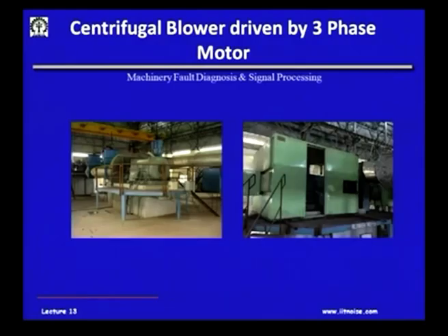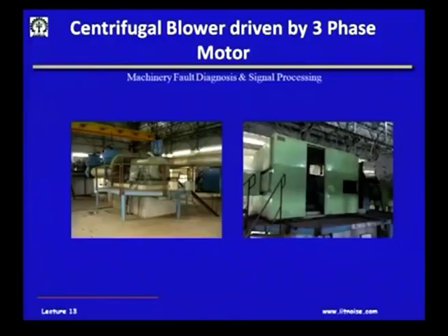Now, in this single room, because there are 5 blowers, what happens if one of them is running at a frequency or a speed little less than even 1 RPM or on a few RPMs, the frequency of these machines will be different, and because they are close by, the phenomenon of beating is going to occur. And if you enter such a place, you will hear this kind of a loud decreasing